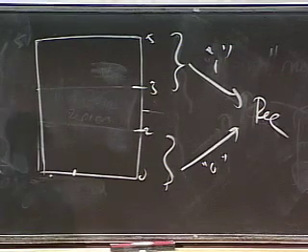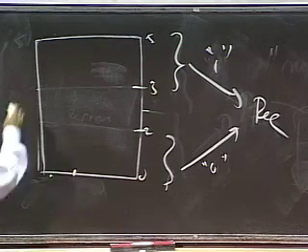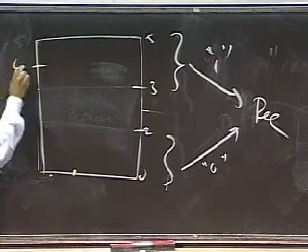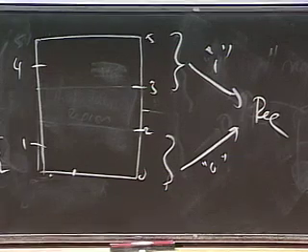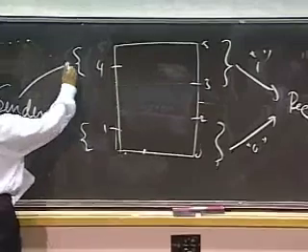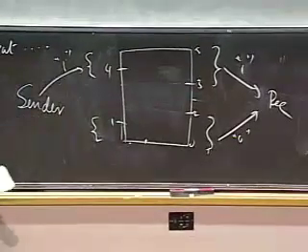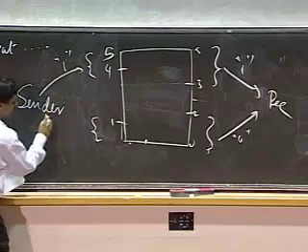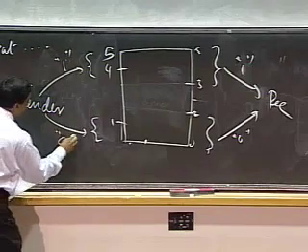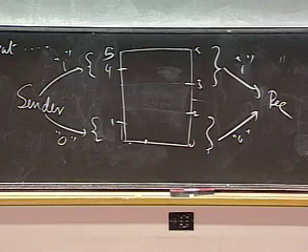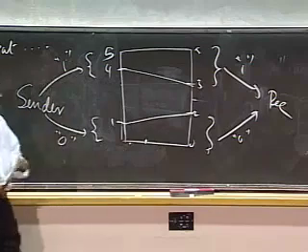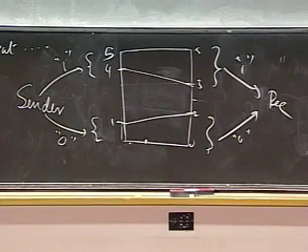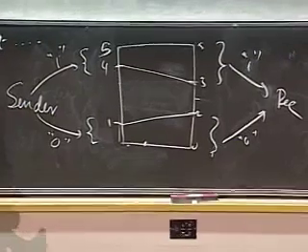So what I'm going to do is hold the sender to tougher standards, maybe 4 volts. That is, tell the sender that if you want to send a 0 or a 1, for a 1, you have to send a value between 4 and 5, and for a 0, a value between 0 and 1. So the sender is now held to tougher standards. So this is what my chart looks like. So now I do have some noise margin.